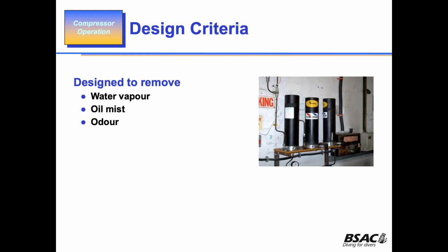And the worst thing that can happen is you've got oxygen in there. You've got 21% oxygen in there, and you get water. So you get oxidizing, and you'll get corrosion inside the cylinder. It's got a perfect place for it. And that's why they look at your cylinder to make sure that you haven't had moisture or water in it, because it's got the ideal conditions to cause corrosion.